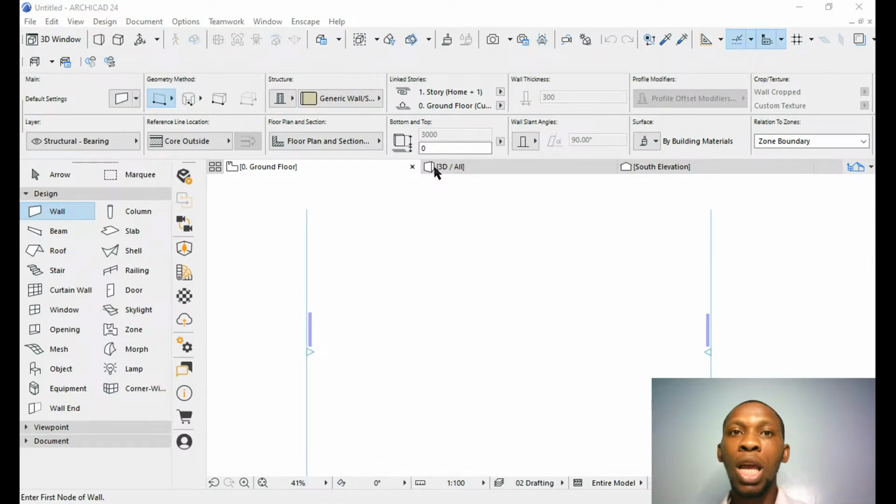If I'm talking about scale, if I click on this now, you see there are different scales here, and these different scales are used for different professionals, right? For architecture and then interior design, the scale that we work with mostly is scale 1 is to 100. Say my scale is 1 is to 100 and I want to print my documents in an A3 format. If I'm working on scale 1 is to 100, depending on the size of my paper, I can use this scale to scale down my drawing to fit the size of my paper.